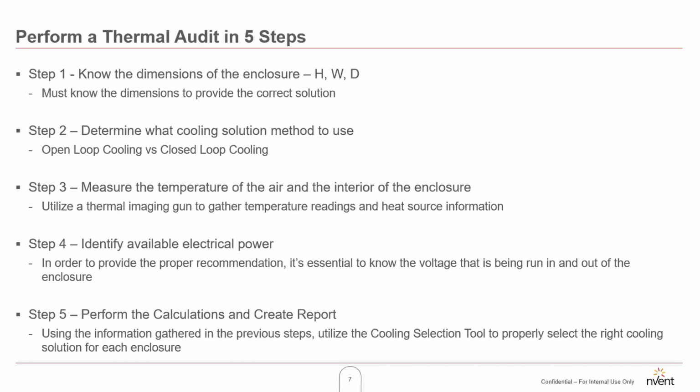Also, most manufacturers list the date of production on the unit, and you can make a note of this in your report as well. If the AC is over 10 years old but still working, I like to make a note of that and get it on the customer's radar that it's over a decade old, and ACs usually don't last more than 10, 15 years. Just get it on the radar that it may be something to be replaced in the next few years.